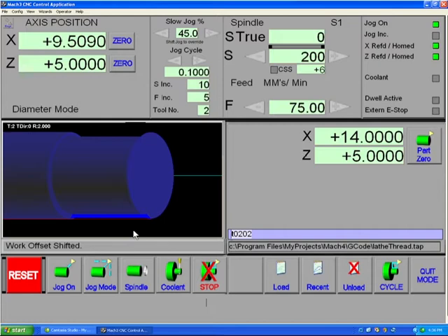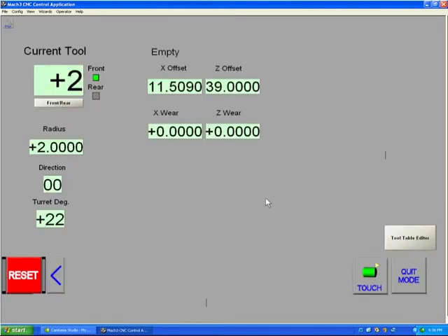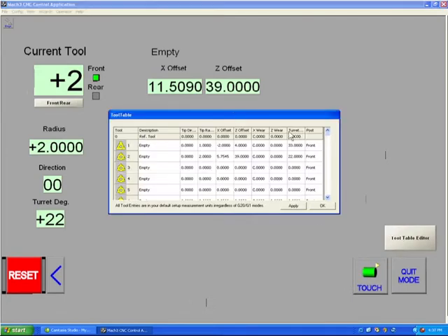if we were on our manual screens and we moved into the piece and we jogged in so that a tool, any particular tool, is touching our diameter, and we know, because we've already set the diameter as 14 in this case, to adjust tool lengths, you only need to jog in to touch the tool, return to your tool table page, and hit touch. Whatever tool is currently selected will now be zeroed in its X and Z length to be equal to that position. You can fill a tool table this way simply by selecting tool after tool and zeroing it with the touch position. The tool table will remember these values and will keep them in mind next time you start the program. Hitting touch when you're not sure whether you're zeroed will simply invalidate that tool because the numbers that are